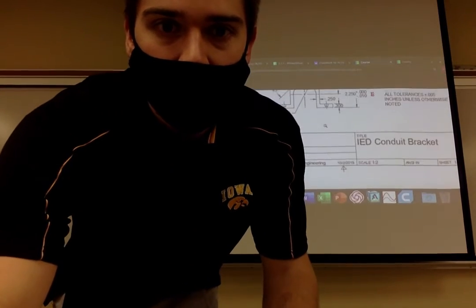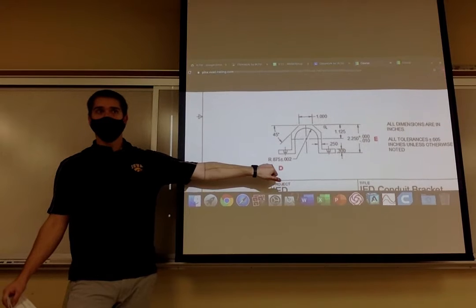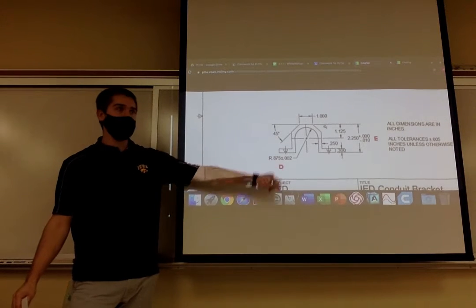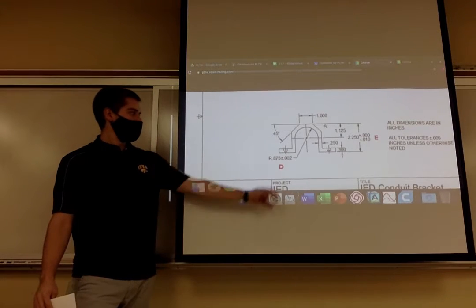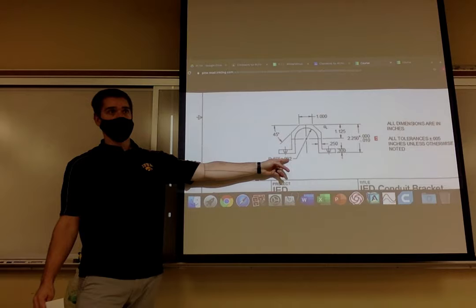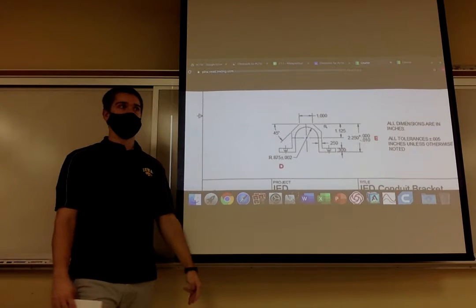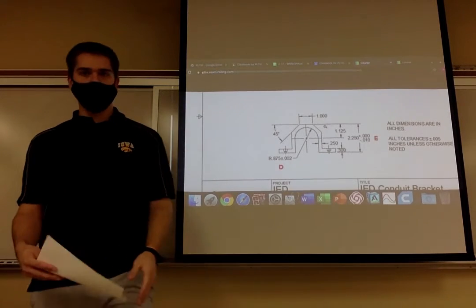Alright. D, down here. What type? Bilateral, plus or minus. You can have error above or below my dimension. Total tolerance? 0.004, good. My total range is I can go 0.02 above, 0.02 below.